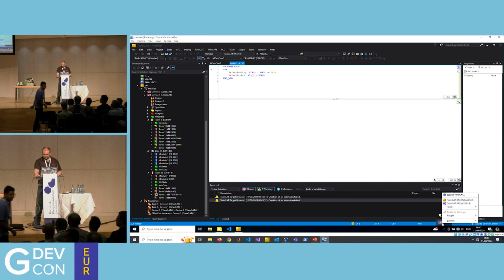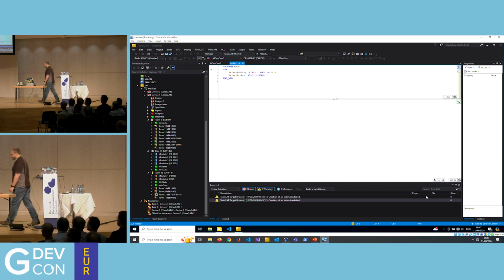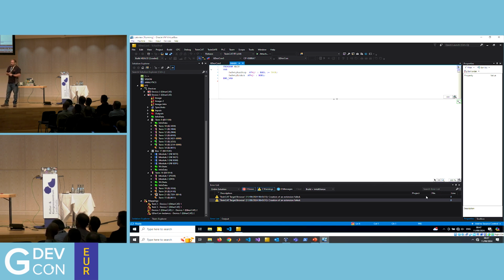My question is, how would you compare the Beckhoff ADS to OPC UA, which is also non-real-time communication with PLCs? I mean, the thing about ADS is that it's Beckhoff specific. Okay. Yeah, but it is an open standard, so you can use ADS and develop your own servers and clients for other machine vendors, PCs. We have customers that do that. The thing about OPC UA is that all the PLC vendors have signed up to OPC UA and they all implement it and it's all the same, right? So that's the thing that OPC gives you.